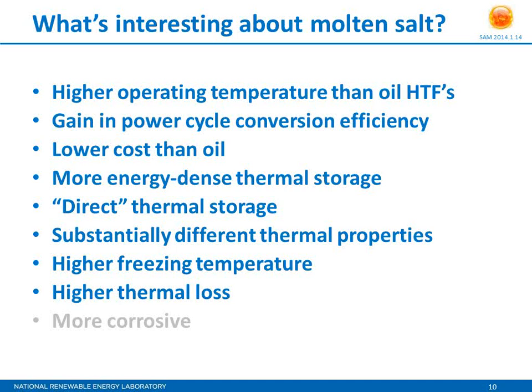If you use a salt in the field, you can actually do the direct storage case where you are not doing an intermediate heat exchanger, so you don't have to buy that heat exchanger. You don't have to incur the heat exchange penalties across that system, and so it's more efficient and less costly. Now, in terms of the benefits, those are really the 5 that I've identified. There are some other differences that are just interesting to look at, and so we'll also talk about those.